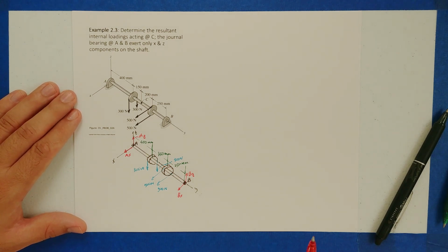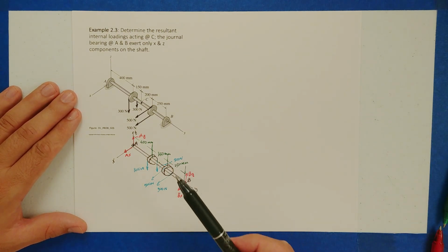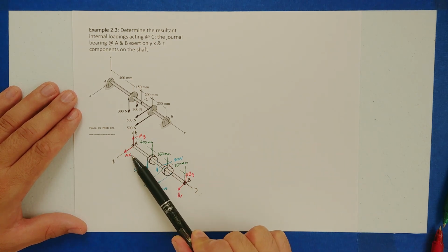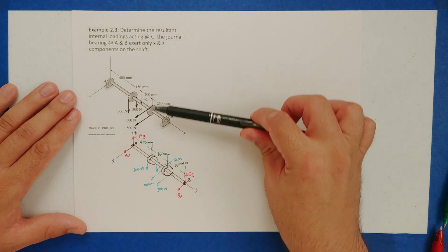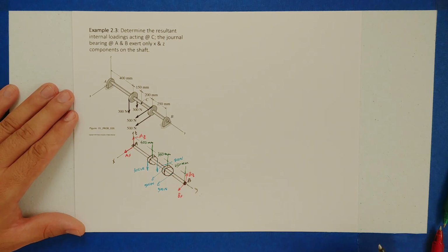So now let's solve for reaction forces in 3D. Alrighty, so how do we do that? Well, we can try summing forces. If I sum forces about the X, I'm going to have AX and BX, right? Two unknowns, one equation, not a good one. If I sum forces in the Z direction, two unknowns, not a good approach. So it's going to be to our advantage to start instead with summing moments, right? So we're going to sum moments.